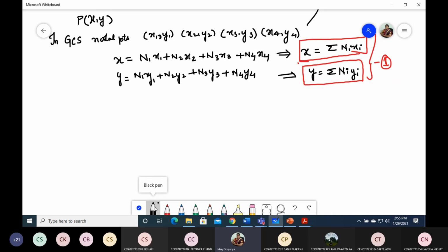Until unit 3, using shape functions we can find out nodal or elemental displacements. But from unit 4, in the isoparametric concept, shape functions are used to define deflection, and they are also used to derive geometry.